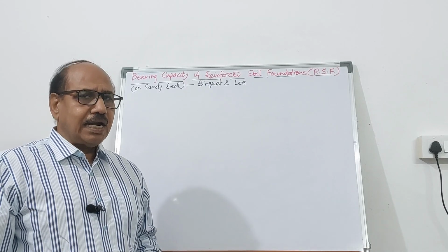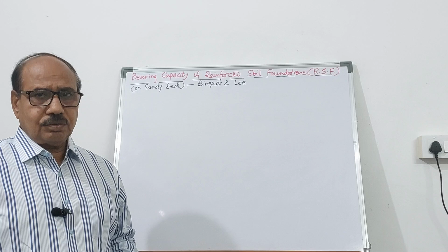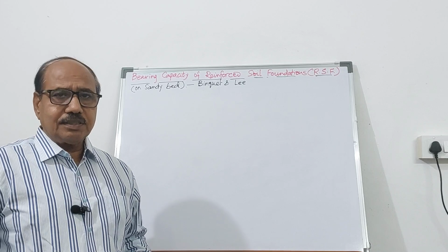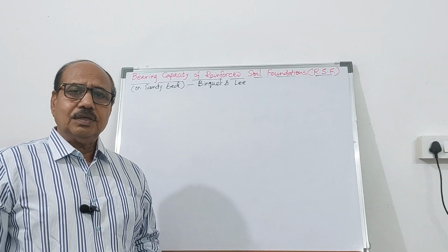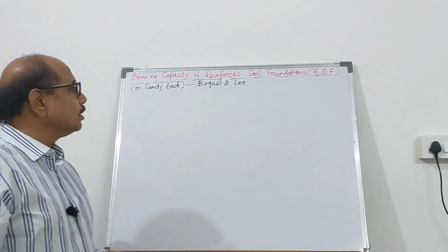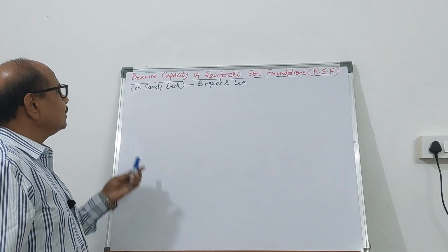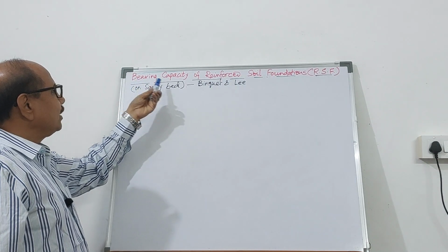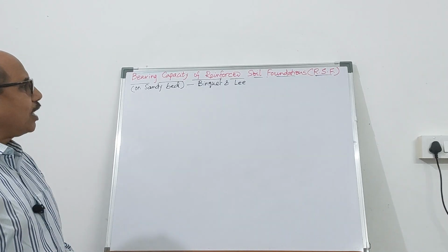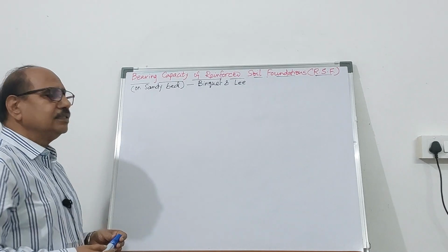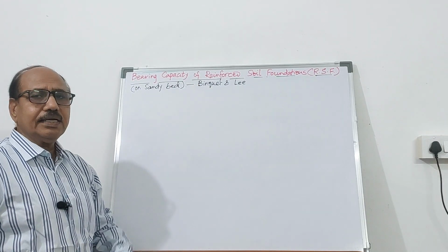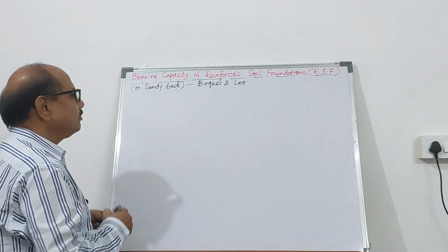That's a considerable improvement in bearing capacity with the help of geosynthetic reinforcement in any foundation. So, in continuation with that, what are the analytical tools? How can we quantify the bearing capacity and the other related parameters? This analysis is the bearing capacity of a reinforced soil foundation, RSF, on a sandy bed. The first paper on reinforced soil foundation was given by Binquet and Lee way back in 1975.